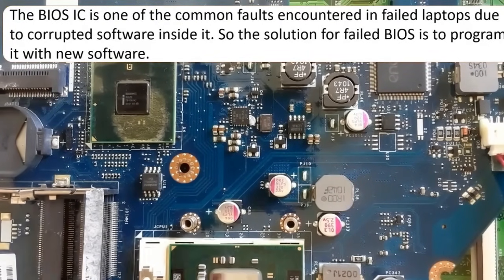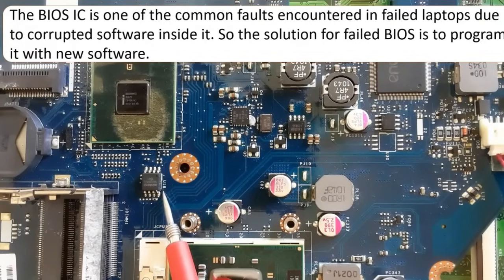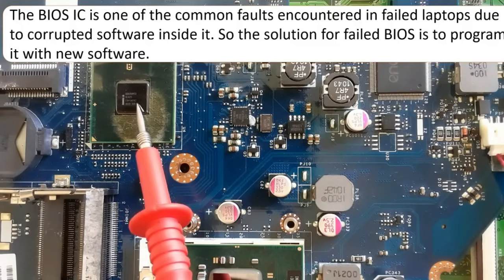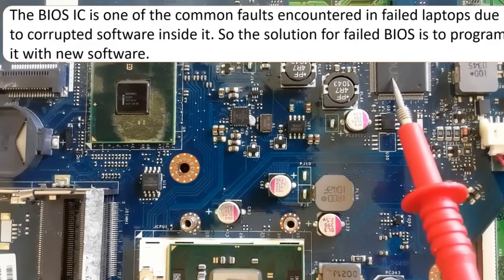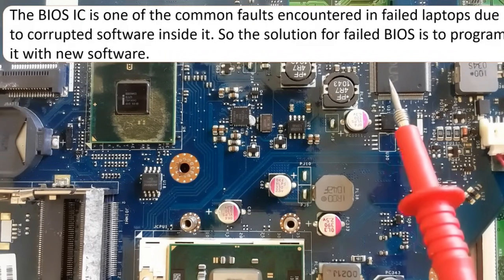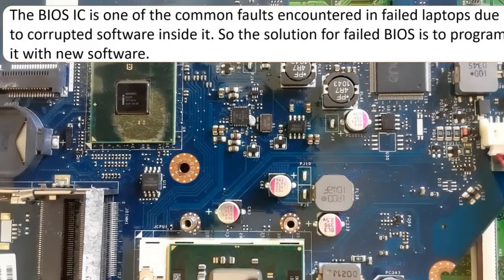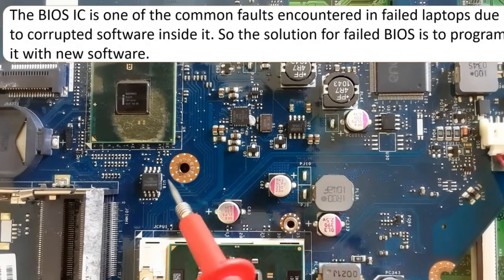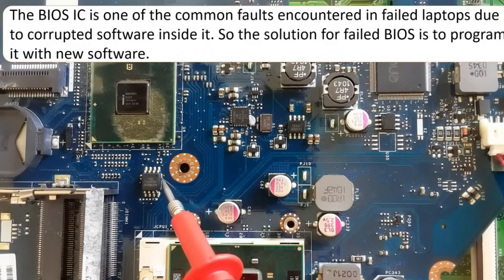Here we have another motherboard, where we're going to see another BIOS, as you can see. This is another 8-pin BIOS. Here we have the ICH, and this is the Super I/O. Usually you can find the BIOS near the ICH or the Super I/O, so these three components are usually near each other.